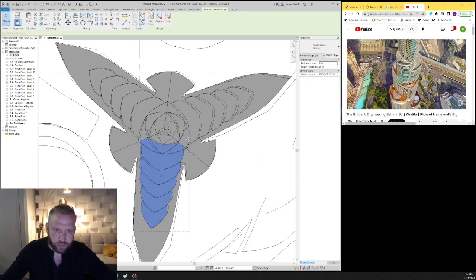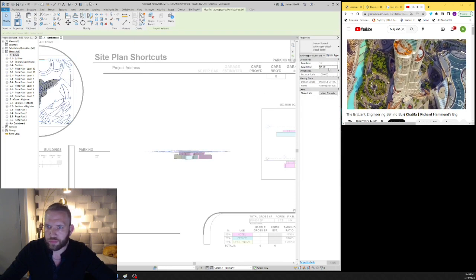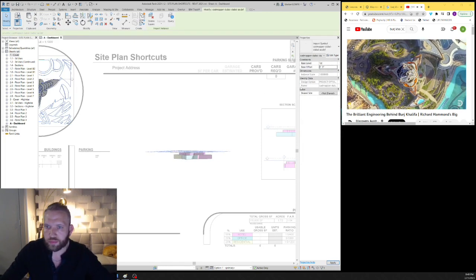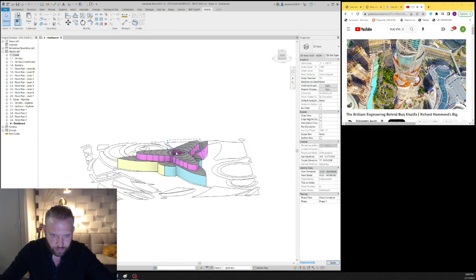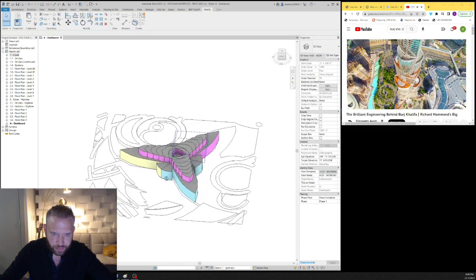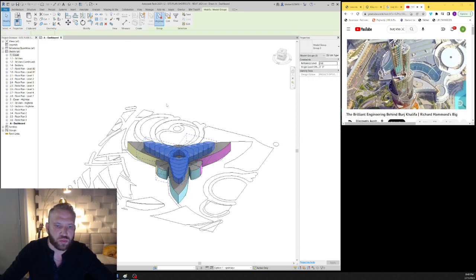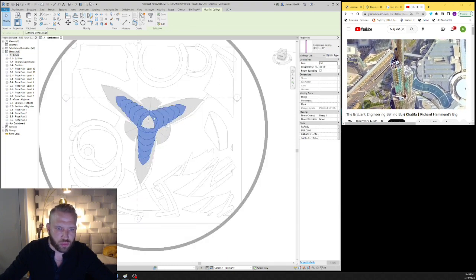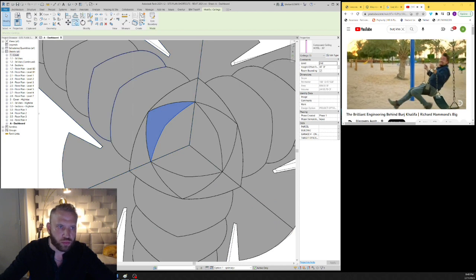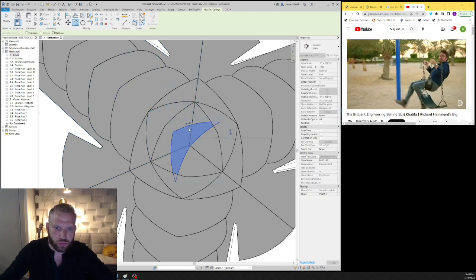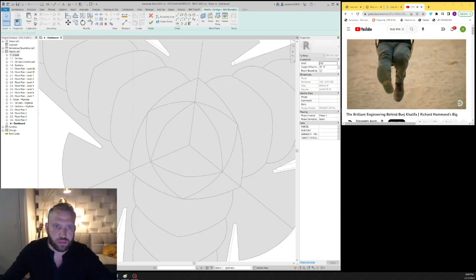In order to make sure the wind is well and truly confused, the Burj Khalifa isn't square like a traditional skyscraper. It's Y-shaped. It gets narrower as it rises, its edges are curved, and its cross-section is constantly changing. And this design breaks up the force of the wind. What the Burj does is what my legs are doing now, which is not working in harmony with the natural frequency of the skyscraper, and as a result, there's barely any swing getting going.